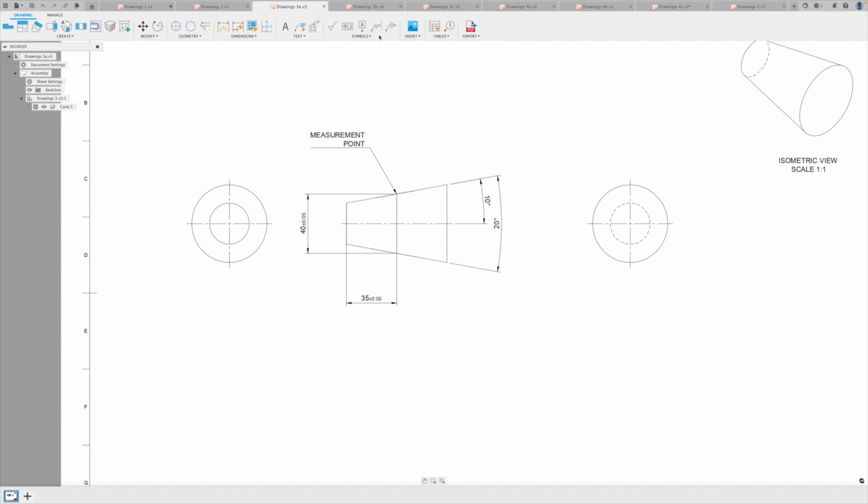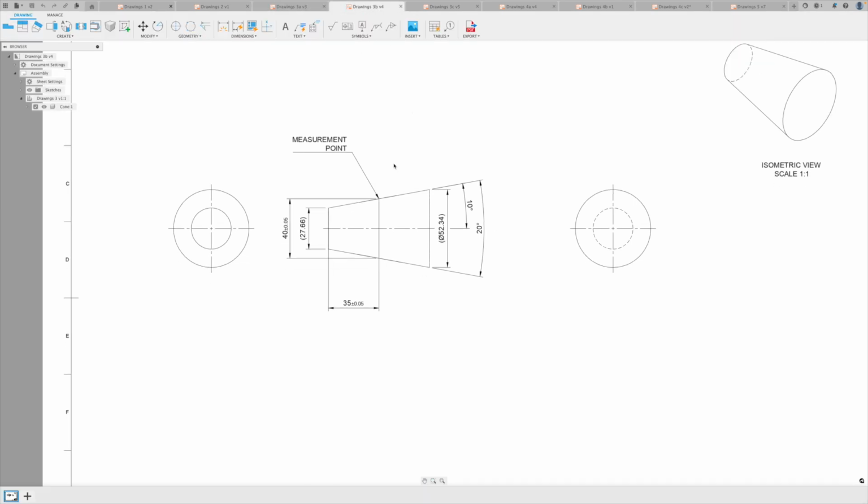These should be given as reference dimensions, which are shown in this version of the drawing. You may choose to set up your inspection once to measure the functional diameter and distance, but the next time a batch of these parts comes in, you can simply measure the end diameters and length, which will make the inspection quicker and cheaper, leading to cost savings on your parts.